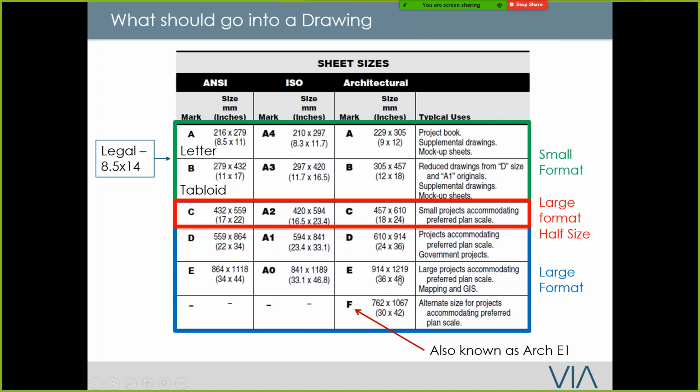You can go like 72 inches, which is like 5 feet. Just keep in mind you're restrained to 36 inches as your maximum, because sometimes you're going to do a transit line that stretches for miles, and you have to fit those into a drawing. So you have to create a custom size. The width has to be 36 inches.